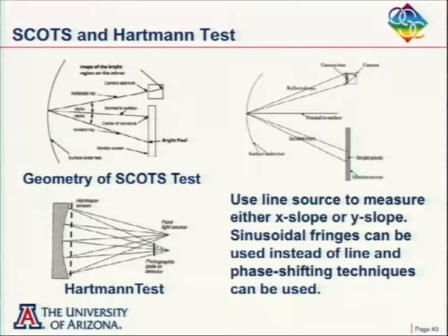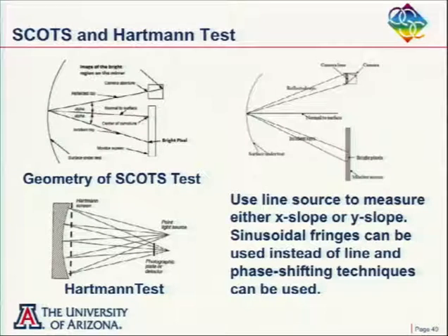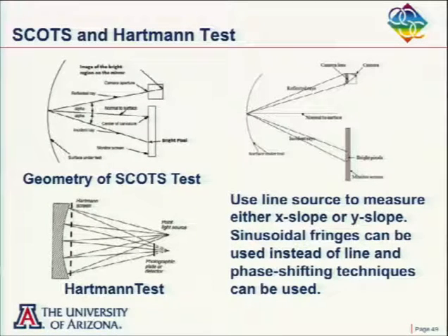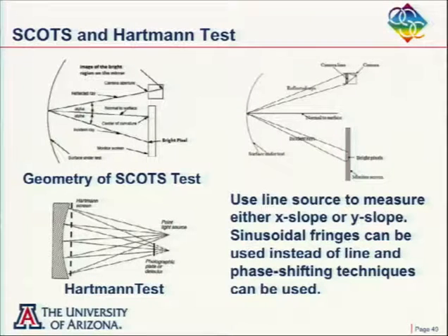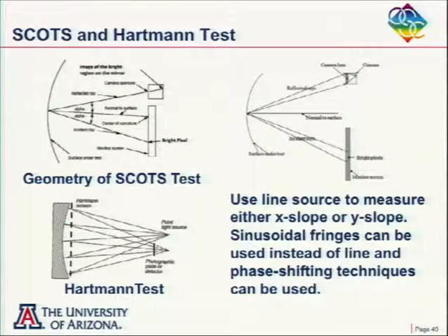Theoretically speaking, this is very much what you just said. So basically, like for the GMT, we take 16 phase shifting steps per period, and we take that at one pointing. We unwrap that phase, and then we correct for distortion before we get the slope maps. And then we integrate the slope maps to get the surface maps.